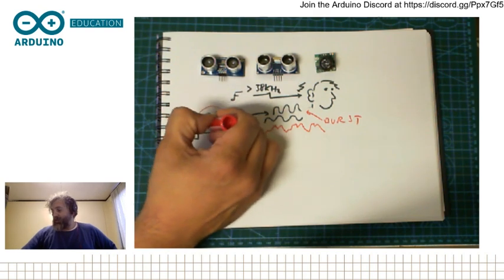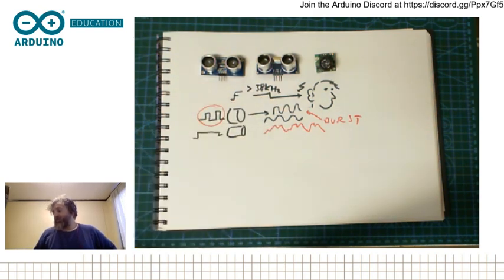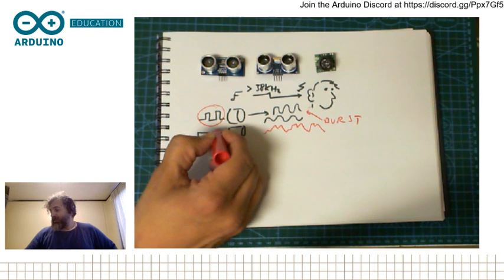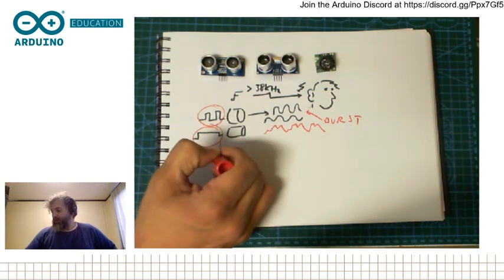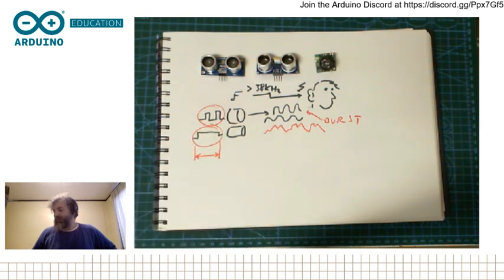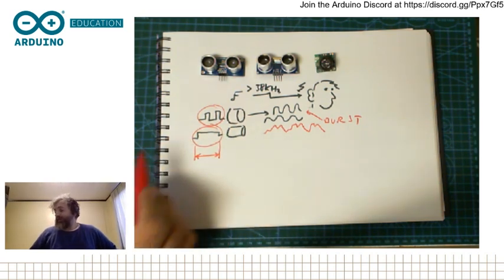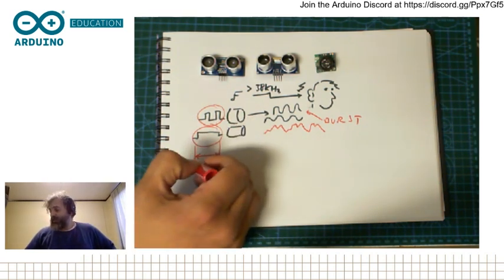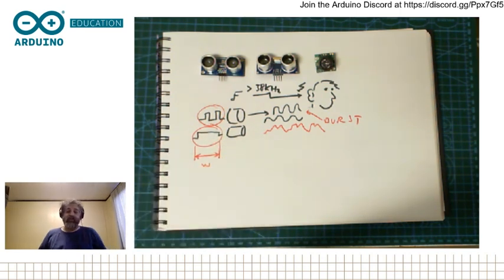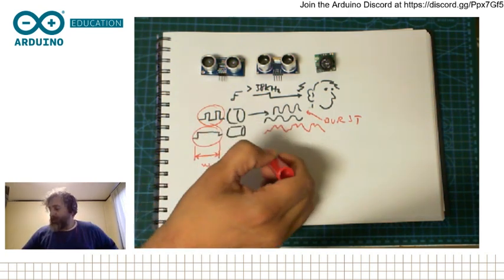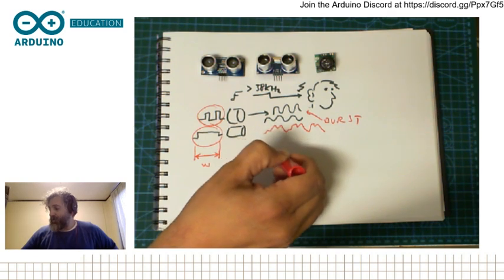So the signal is what Arduino needs to get through the transceiver. The signal is what we get from the transceiver. And the signal is actually made in a way that translates the distance into a pulse of a certain width. And this width is computed in terms of the flying time of the signal. Because we know the sound goes typically at 340 meters per second.